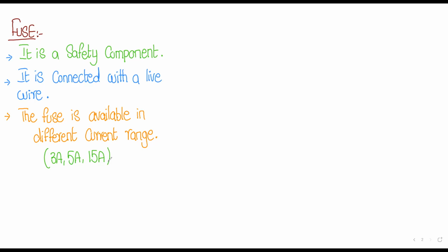a 15 ampere range fuse in that device, the device which is operating on 4.5 ampere current, if the current increases to 10 or 11 ampere, the fuse will not melt because the range of the fuse is 15 ampere. So you need to pick the correct fuse according to the given value of the circuit, right? And how do you come to know the exact range of the fuse? How do we know which fuse is suitable for our device? By testing the component or anything.